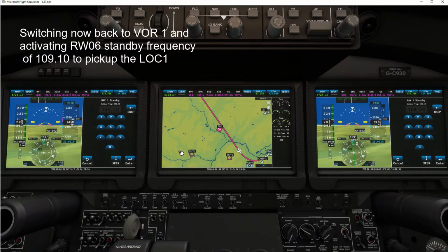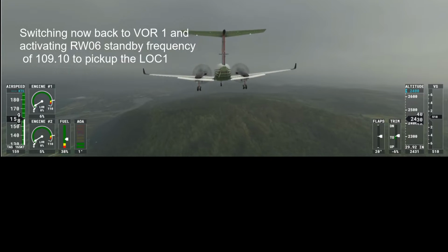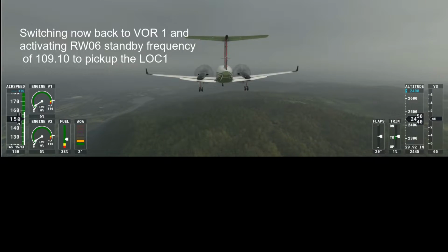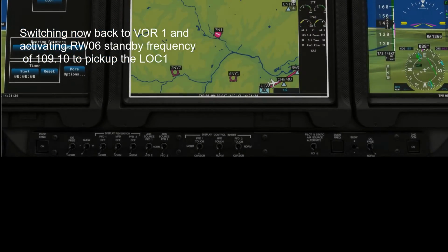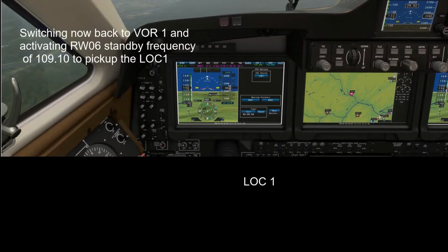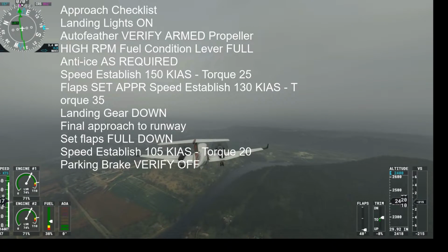And then I'll just use a manual landing. I'll take autopilot off. So I'll descend, but I'll leave autopilot on just to line me up with the runway. So here I didn't need to select a course because the localizer will actually send out a signal to line the aircraft up.